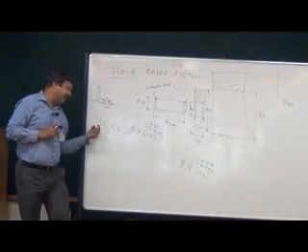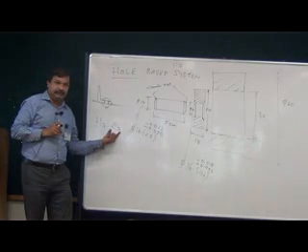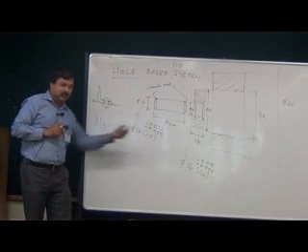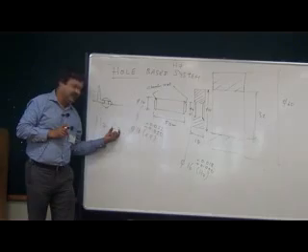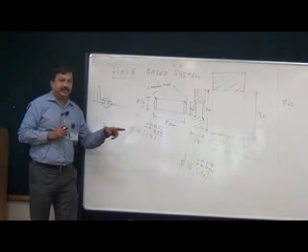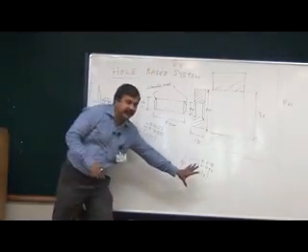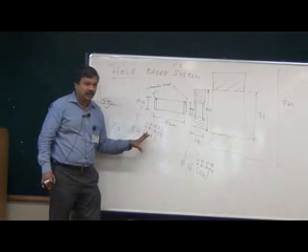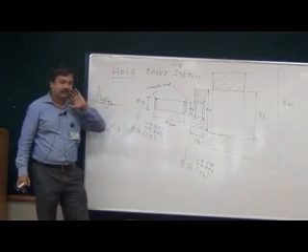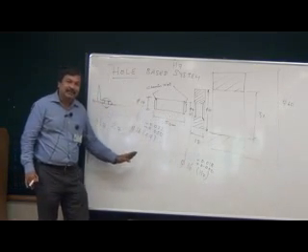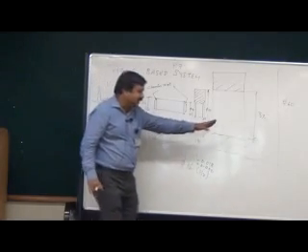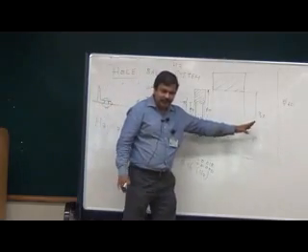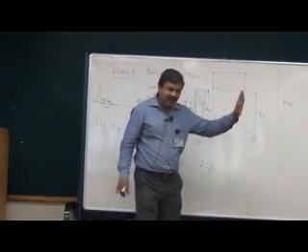So the tolerance span is H7, E7. The capital letter stands for the hole feature. The small letter stands for the shaft feature. So I have obtained the required tolerance for free running. Now shall we do a similar exercise for the 32 mm diameter between the bush and the housing?